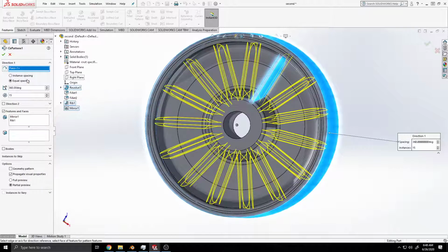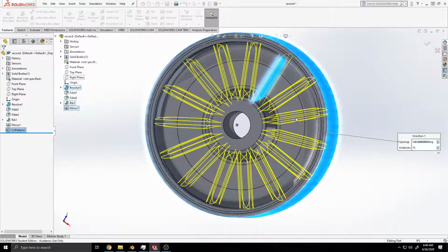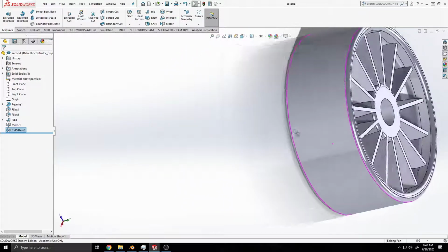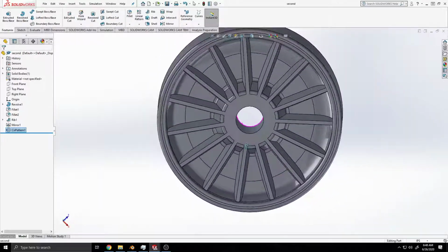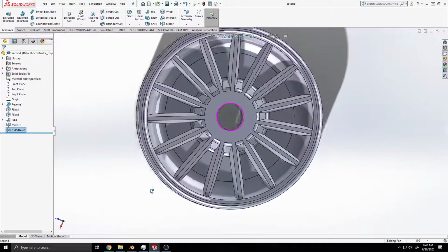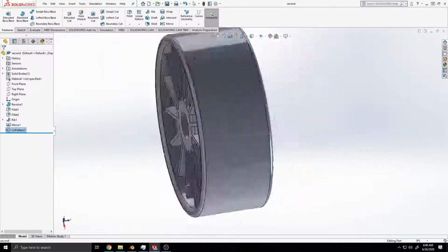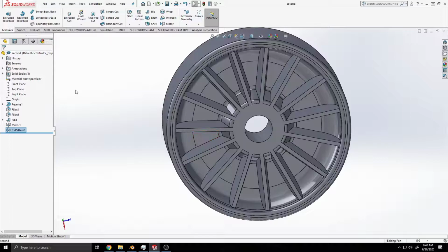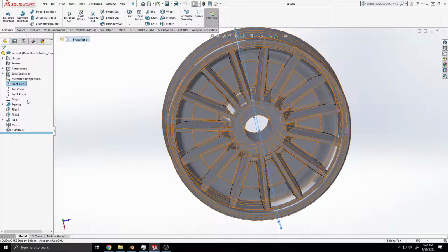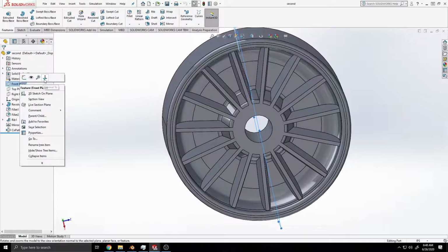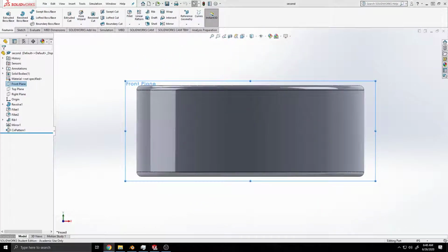And so you can see we have these blades in there. Okay, the next thing we're going to do is I'm going to show you a neat little trick here. Revolve Cut. Select the front plane again and start a sketch. Hit your space bar and click on the front view orientation, or Control 1 for the fast keys.